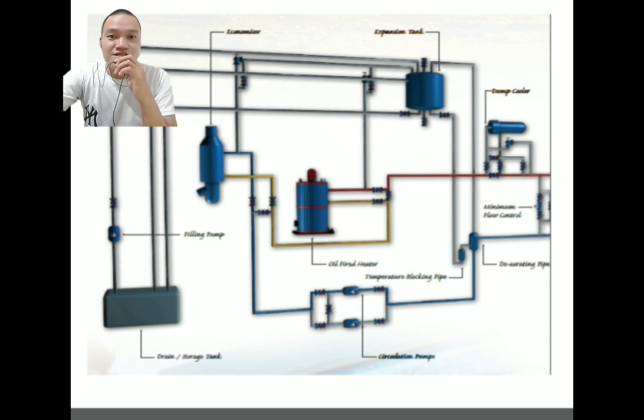Third procedure is these increment steps are done by taking a system from 70 °F or 21 °C and increasing the heat by 20 °F and letting the system run until the temperature on the heater reaches 90 °F or 32 °C. So once the heater reads that, then dial it up another 20 °F or 11 °C. Once your heat transfer fluid is 10 centipoise or less, you can dial the heater to your operating temperature.